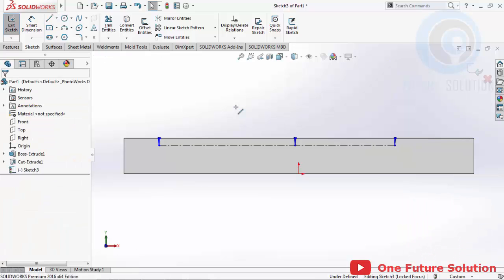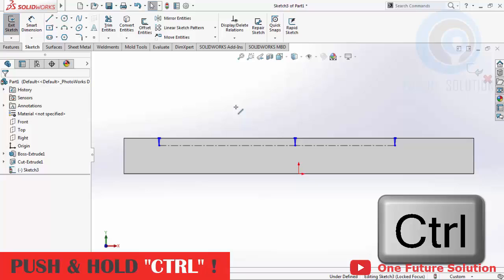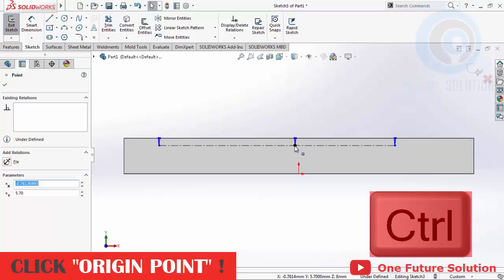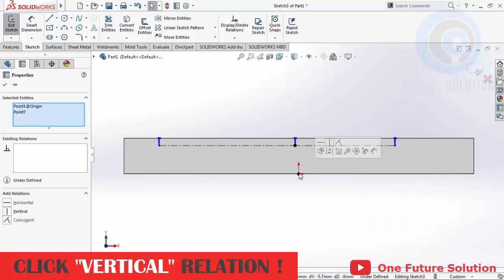Now we will set the position of all three triangle shapes with some relations. Push and hold the Control button to select more items. Click the middle bottom point of the triangle shape. Then click the origin point in the graphic area. Choose and click Vertical Relation to make that point be in a vertical position.